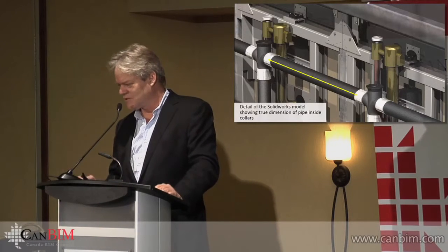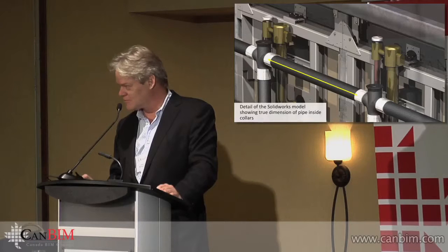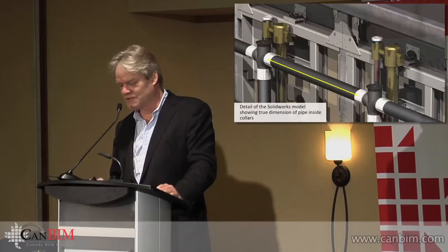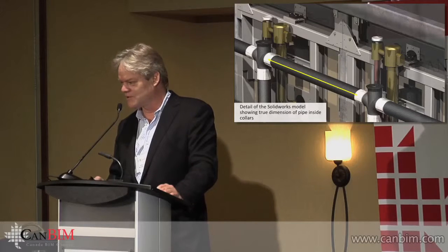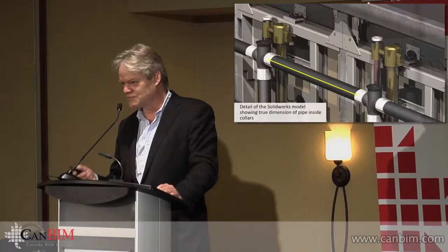You see there that yellow arrow, the heads could be larger. It shows the pipe fitting inside the collar. The collar's been modeled. It's got a little annular ring inside it. It's got a tolerance envelope around it. So when you build the plumbing of this unit out of these components, you then get the length of the pipe, and it goes into your bill of materials.